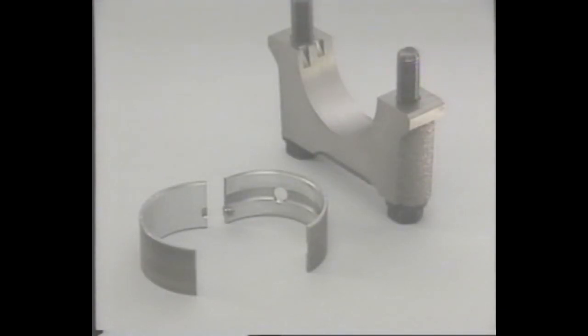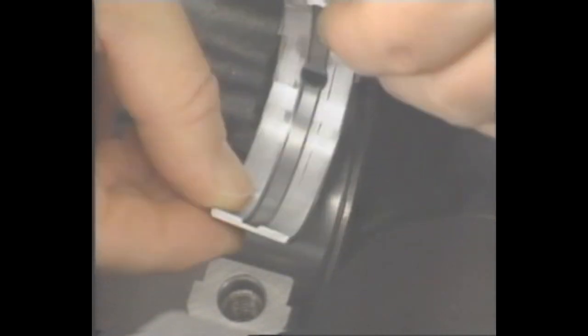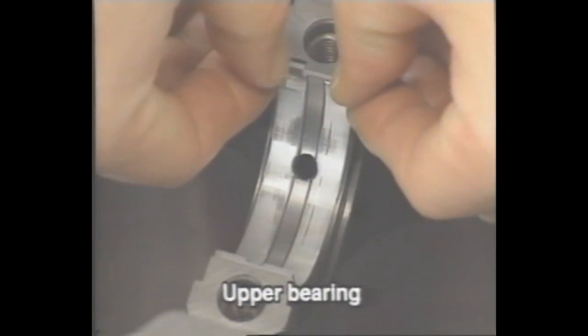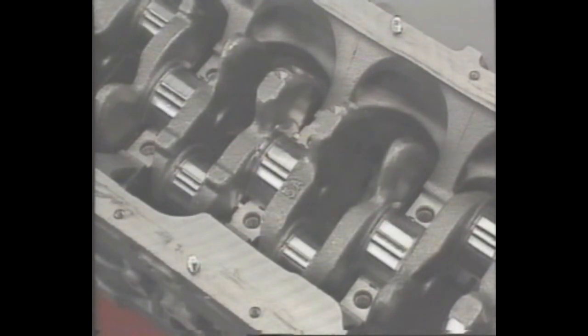Here, let's look at the method of measuring the oil clearance of each crankshaft bearing. Install the upper bearing on each bearing cap, aligning the oil holes. Place the crankshaft on the cylinder block.